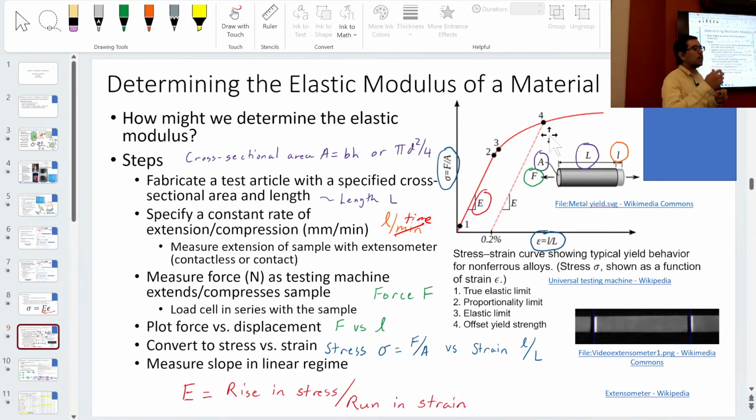You can actually permanently deform the outer surface of a material mechanically, essentially putting lots of divots in it, okay? One way of doing this is called shot peening. Okay, so you can shoot a lot of balls at it on the outside and it will cause permanent deformation, which actually increases its yield strength on the outside.